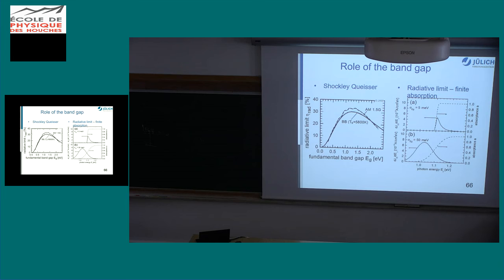Okay, in an almost step function here. That's not really a step function. What we have here is now saying, okay, maybe we have fluctuations of the band gap energy, it's not the same all over the entire absorber material. You have, for instance, in CIGS, at some places more gallium, less indium, and the other way around. So the band gap is not only a single band gap, but many band gaps, and we can model this by having a band gap distribution.